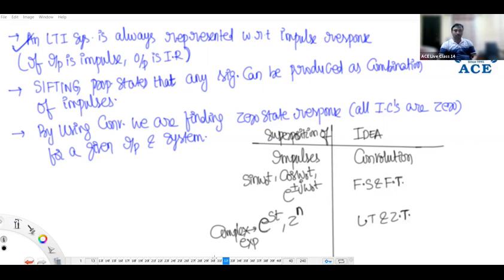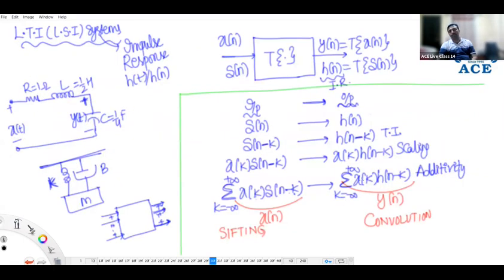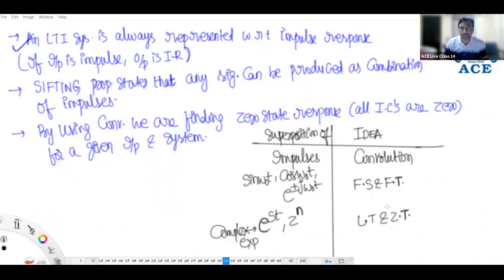Please go back to the 30th slide. In the 30th slide, we proved the discrete convolution formula, sigma x of k h of n minus k. How is it modified for continuous signals? Recollect, everyone: summation becomes integration. The variable k becomes tau. n is replaced by t. So first let us discuss some examples on continuous convolution, sir.